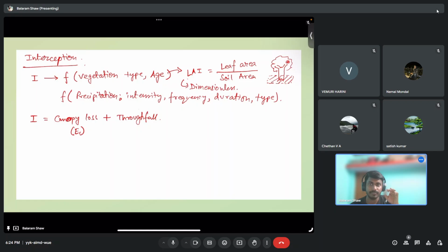Next, this throughfall we will get from a rain gauge itself, but it will be under the canopy. So let's say if in the figure you see, we'll put one rain gauge here and whatever value we are getting from here, we'll deduct from the opening and then we can get the throughfall. And then stem flow: from the main stem of the tree, we'll put a collar there. Okay, and whatever value we are measuring from that collar, we can get the stem flow.